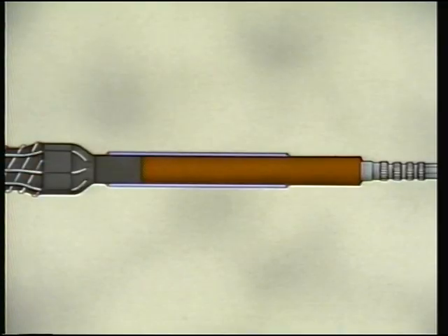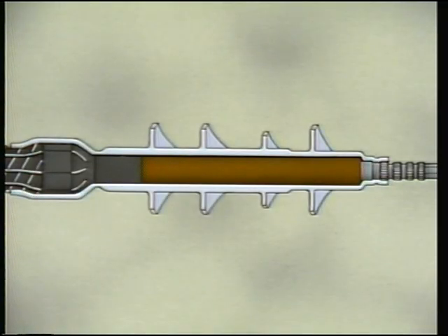When a material with a high K factor is placed over the end of the semiconductive insulation shield, the stress concentration on the insulation is reduced. How this reduction is achieved would require a detailed discussion of electrical theory, but we can say that when a high K factor material is used, it spreads out the voltage stress at the end of the cable shield so that it's effectively reduced to an acceptable level. The outer layer of the cold shrink tube is insulation material. It provides a skirted insulator between the conductor and the grounded insulation shield.